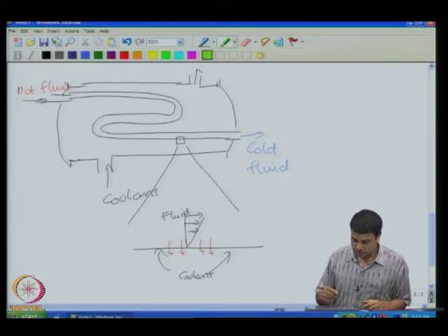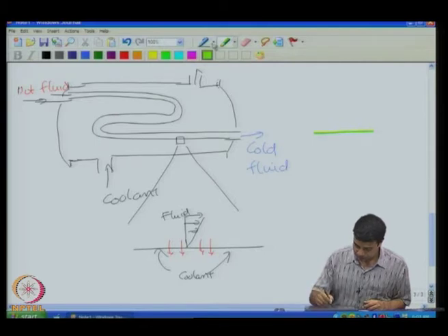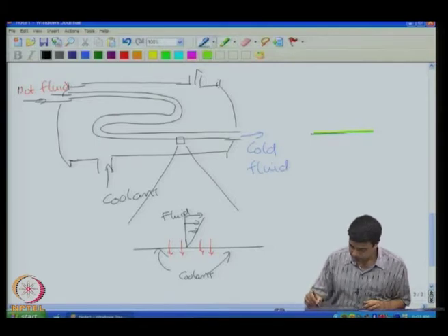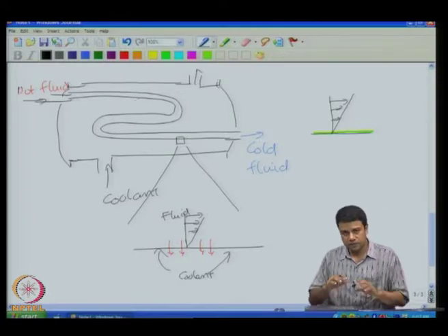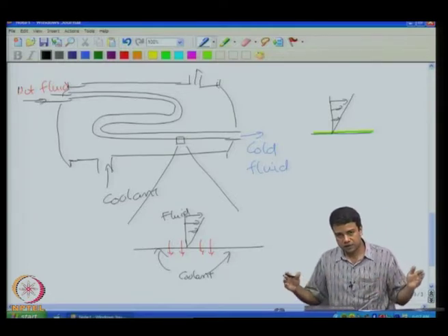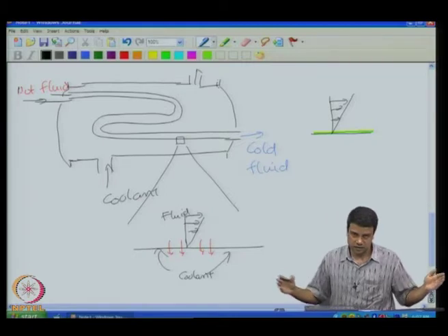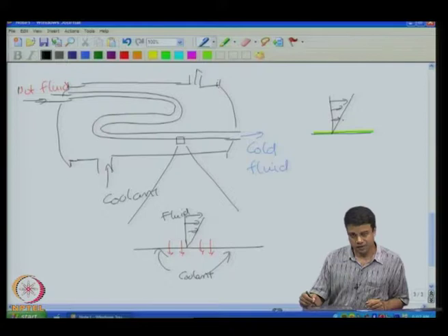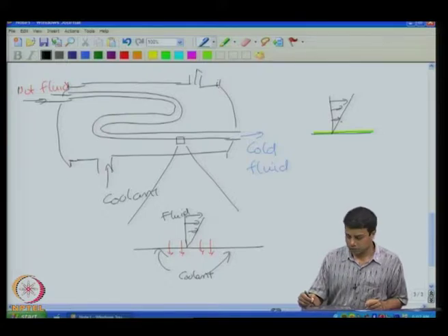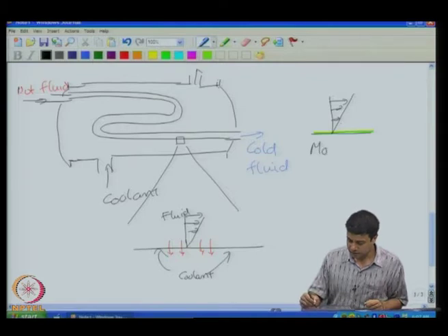Now, this pressure difference compensates for the frictional stress exerted due to the fluid flow at the walls of the tube. The total frictional stress multiplied by the total surface area has got to be equal to the difference in pressure times the cross section across the tube. And this frictional stress, as I said, force per unit area, momentum transported per unit time per unit area, it is a momentum transfer rate.